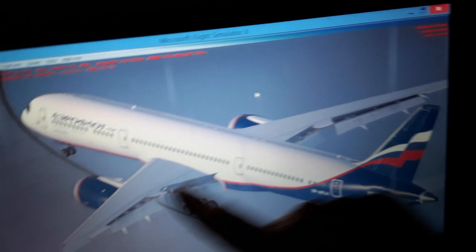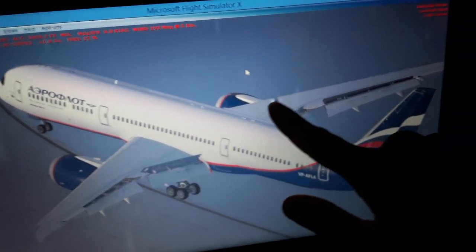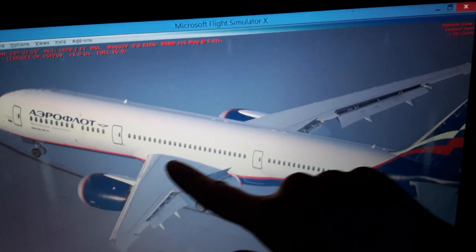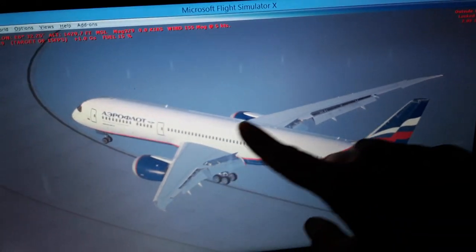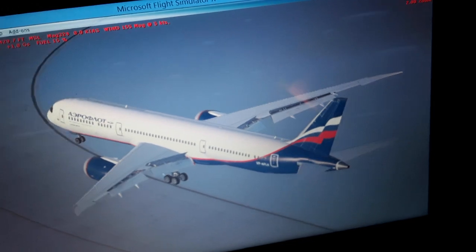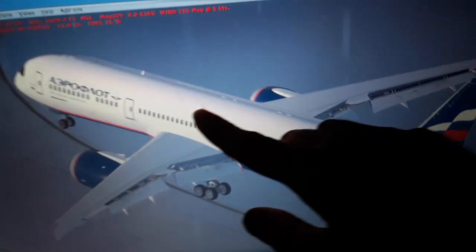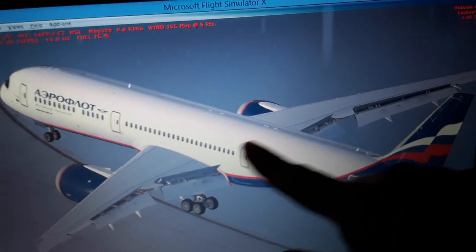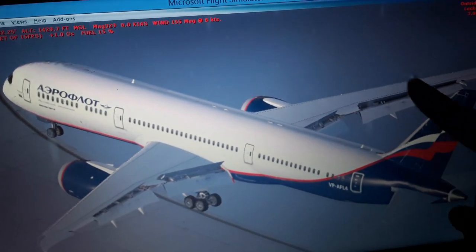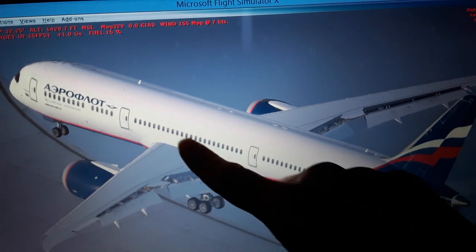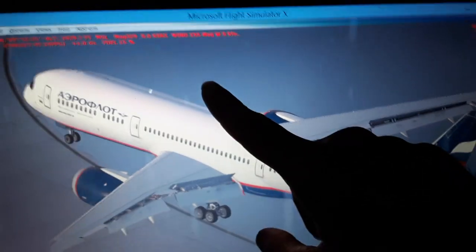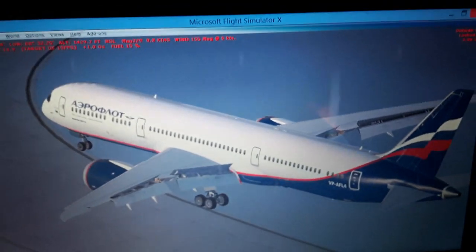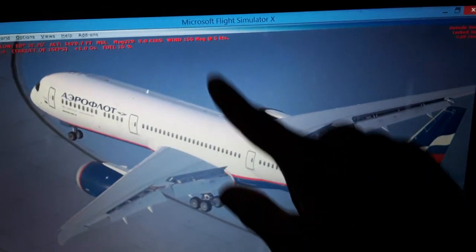We have the mean aerodynamic chord position, the Mach, which is 23% of the mean aerodynamic chord, where the maximum aerodynamic lift occurs in the forward wings. You can see we have the fuel tank, the center tank over here, and the left wing and the right wing fuel tank. So we have 30% in the left and 30% in the right and 10% in the center fuel tanks. So we have the center of gravity here located. You can see, so the center of gravity goes down this way.